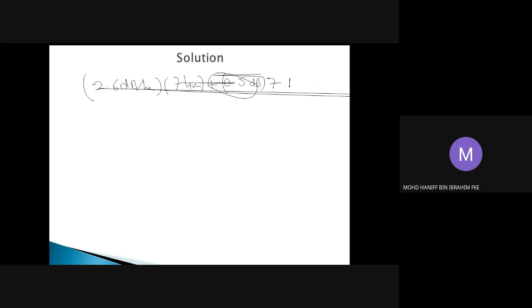Plus the loss due to connectors, 1.5 times 2. And plus your system margin, which is 6 dB.